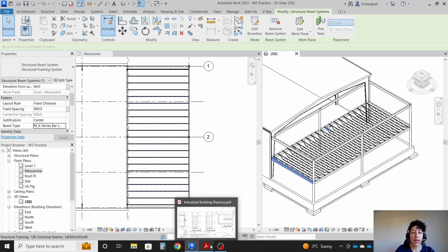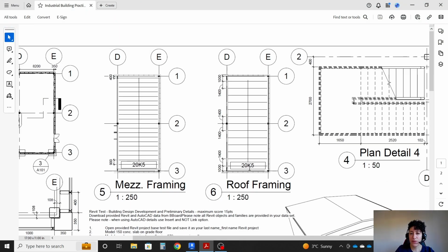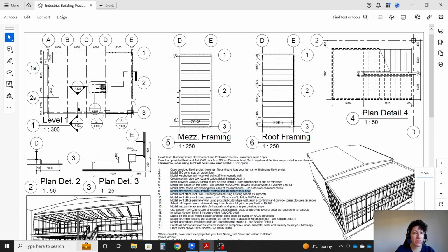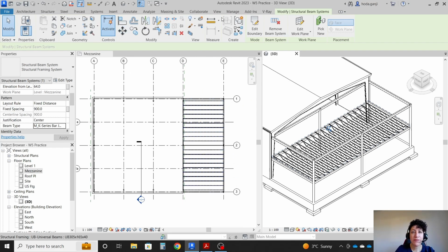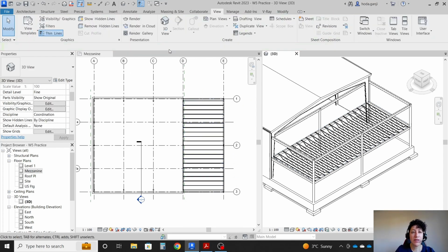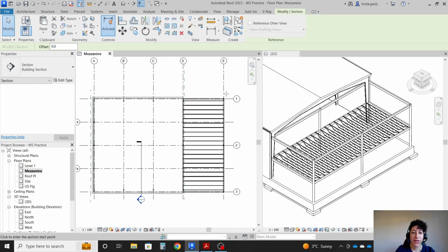We would better take a look at it in section view. We had the different sections from there. We need a second section, this one, which seems to go from between grid B to C to D to E over there. So I'm gonna create a section, maybe right here, it should be good. I'm gonna go with view. I'm gonna hit escape, so we are not in a command. View, click here, see on 3D section, of course, is not active. Section, and we're gonna go from here all the way to around here.